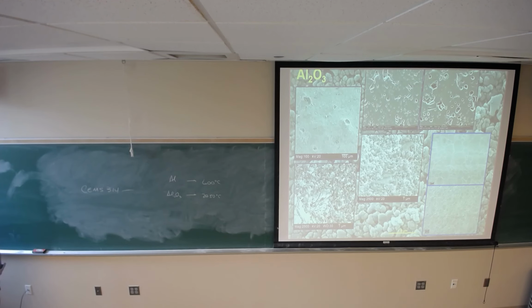We do a lot of stuff with alumina in our processing, and the reason that we do that is because, one, we've spent a lot of time processing alumina, and two, the problems that are associated with processing alumina are pretty much as bad or the worst problem you can run into in processing. So it's perfect for us, okay? Very high attraction forces between the particles.